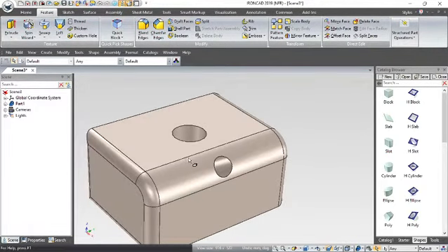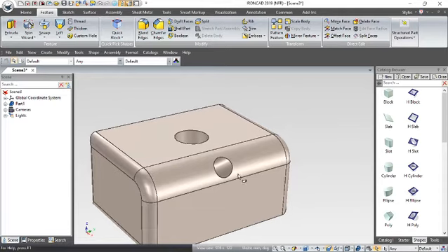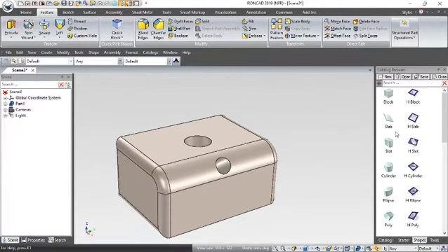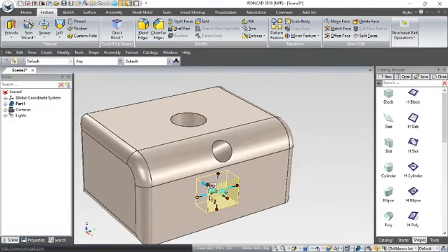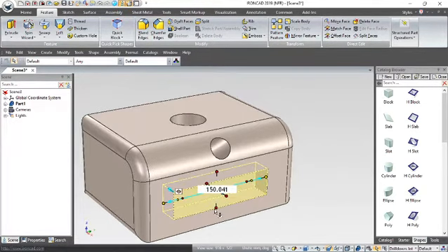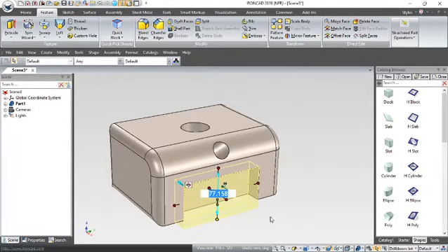And what I'm going to do now is, if you wish, bring in a hollow block. I'll pick a block there and simply put it in here like that. If I want that to be symmetrical about the centre, this is the yellow handle here for the length. I'll pick this one and drag that, come down here a bit, and maybe I want to go all the way down like that, and you see it's a hollow block that I've cut through here.